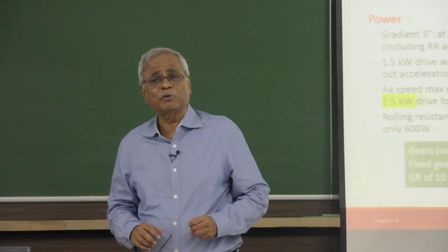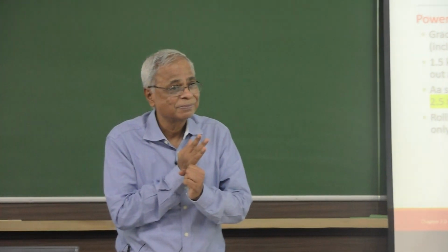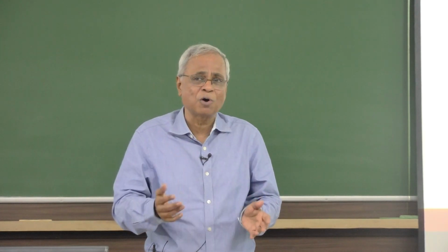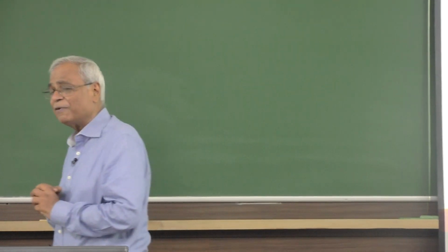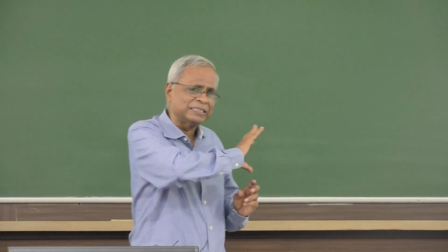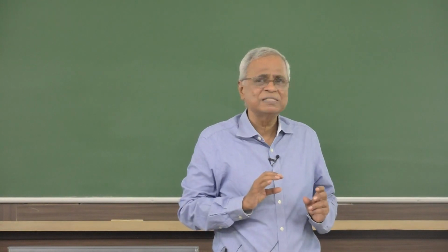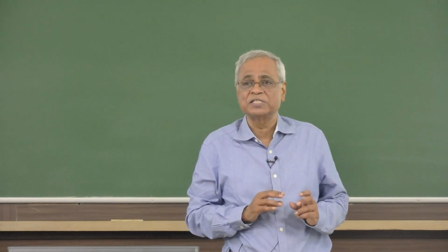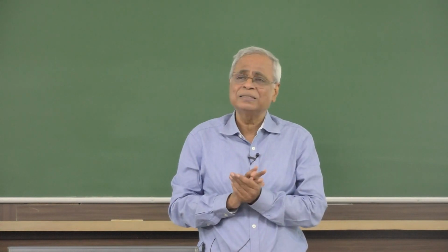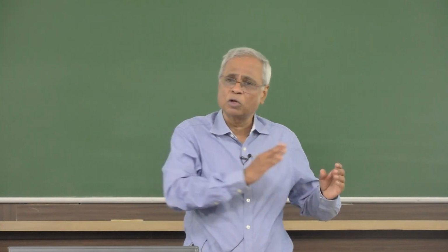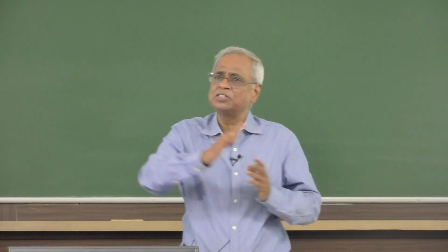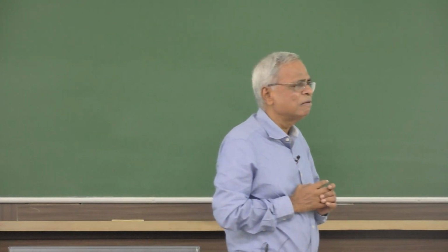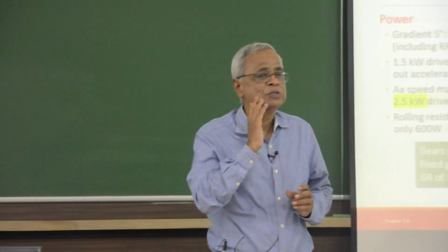Now, changeable gear, what would it require? It would require a clutch, then gears have to be changed, a gearbox has to be there. That whole thing becomes complex. Electric vehicle on the other hand, the motor can actually take a whole range of velocity and RPM and still have a fairly good efficiency, and it is possible therefore to also get a fairly large differential torque. So, generally electric vehicles use only a fixed gear.